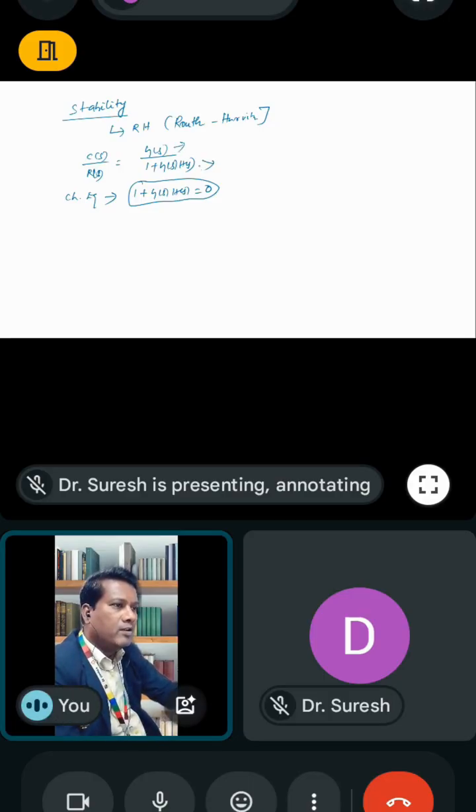Normally the numerator of the transfer function gives the location of zeros, and the denominator gives the location of poles. So the characteristic equation gives the location of closed loop poles. The location of poles decides the stability of the system.